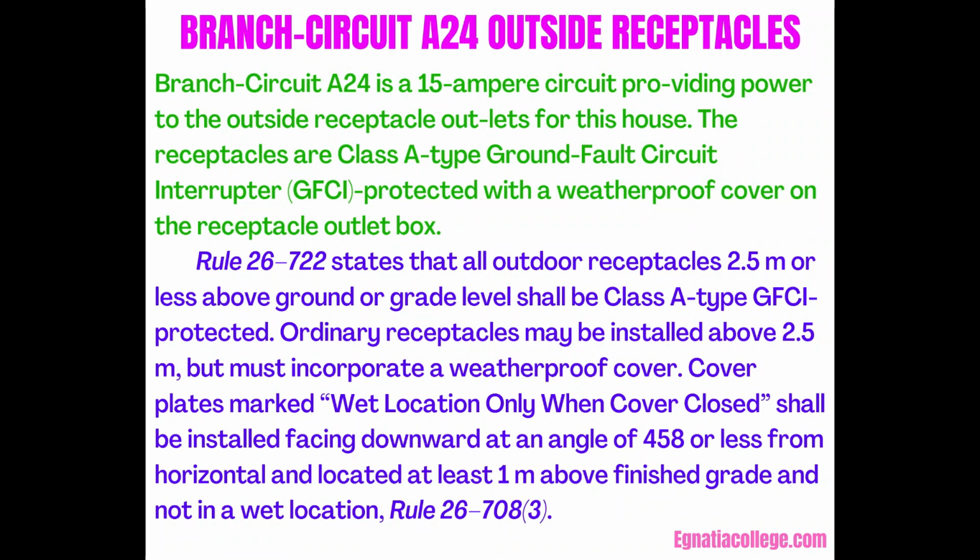Branch circuit A24, outside receptacles. Branch circuit A24 is a 15 ampere circuit providing power to the outside receptacle outlets for this house. The receptacles are Class A Type GFCI (ground fault circuit interrupter) protected, with a weatherproof cover on the receptacle outlet box. Rule